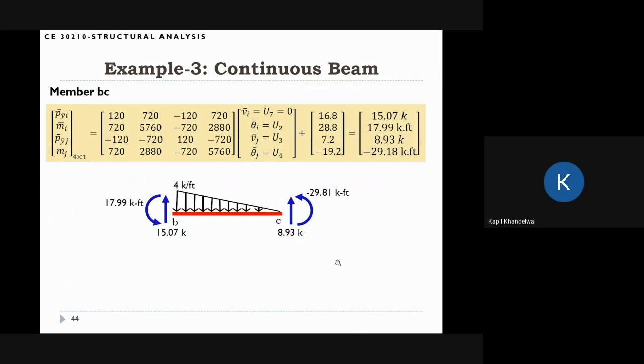And you can see that all these loads are under equilibrium. And if you think very carefully about what's happening, let's say that the maximum magnitude here is 4. So if you take the area of this triangle, that's actually the vertical load acting on the member. If you remember, the span is 12, and the area will be half times 12 times 4.